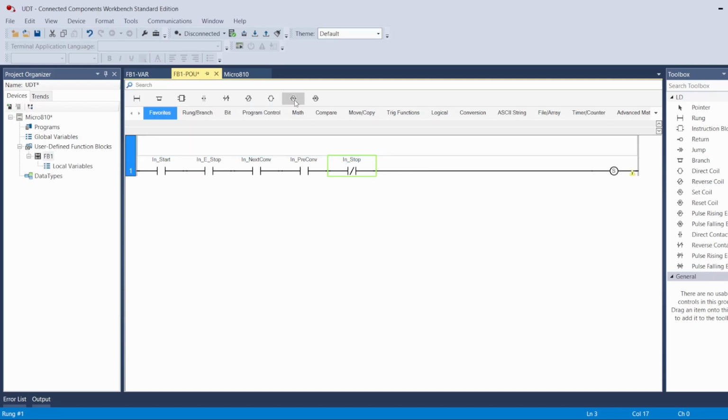I want you to turn on, to give an output signal to start the conveyor. If all of this is true, all of them good, and this is not pressed, then turn on. Give me an output signal to tell me to turn the conveyor on.